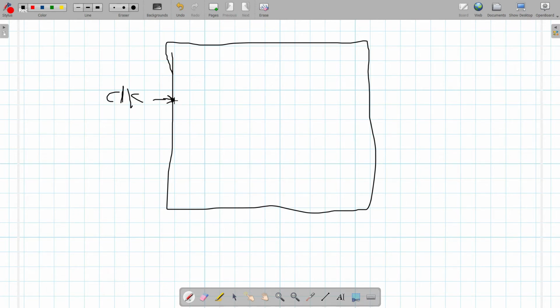If you put a clock on a dedicated global clock pin, then the clock will be able to reach all areas of the FPGA in the fastest time it can. The FPGA is built this way, with really fast buffers that make the clock reliable in all places of the FPGA.